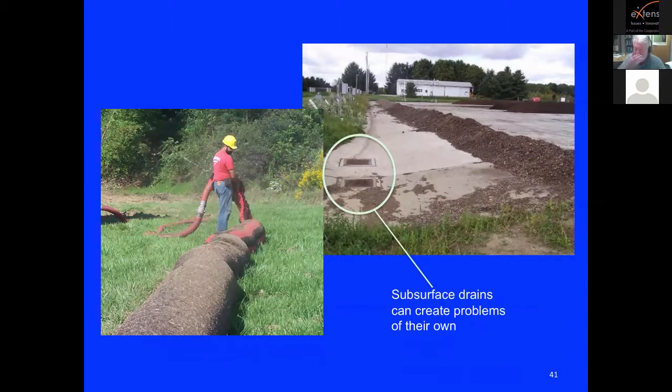These stormwater systems are subsurface. When you go subsurface, you pretty much are guaranteed that you're going to go into an edge area where it goes anaerobic eventually. There'll be a lot of organic matter down there, and it will use up all the available oxygen. Also, periodically, it creates clogs. That's an irritation. But when it goes anaerobic, if you have enough organic matter, you can end up getting basically sewer gases down there. And so you want to be very hesitant about letting any workers go down into this subsurface drainage area. It can be a confined space with hazardous gases. You can get hydrogen sulfide in there. It has happened at a couple of compost sites, and people die. So please think 2 or 3 times before allowing any worker to go in any subsurface drainage area.